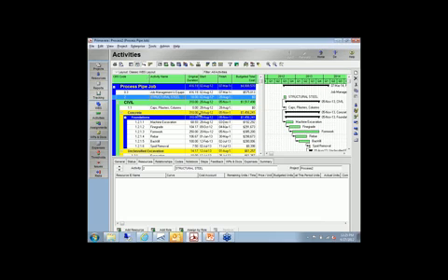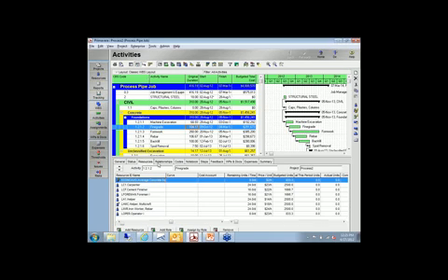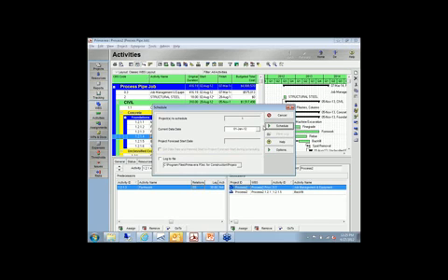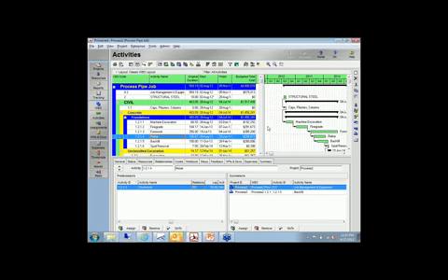Let's do some other things that maybe lengthen the schedule. It's still 416 days, but you can see a lot of this earthwork is happening with start to start connections with a little bit of lag. Let's make some of these finish to start connections, and that way we'll lengthen out the schedule. Maybe we can't do those things as simultaneously as we had hoped. So we'll make a few of these finish to start instead of start to start. Okay, so let's update our schedule now. So now we're up to 589 days in our schedule.